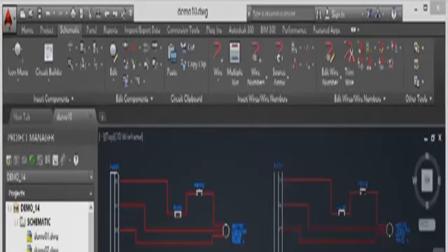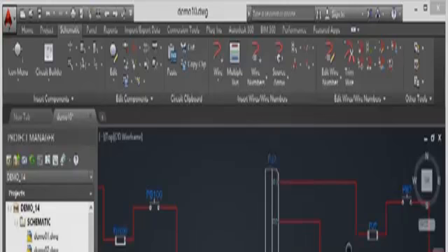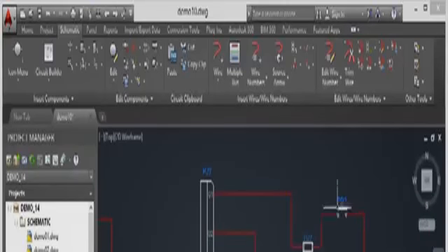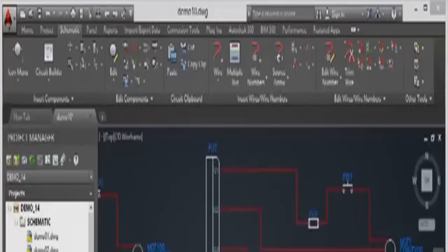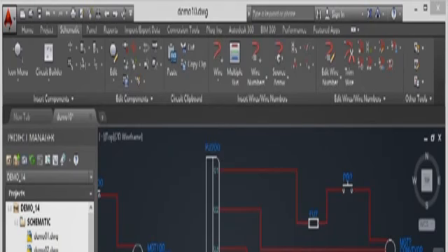Click on OK there. There's my circuit there, an exact replica of the circuit on the left. I just click, and it comes into the drawing, and as you can see, this has now got PJ question mark, FU, fuse question mark, push button question mark, and so on, because it all needs to be tagged. Now what I can do here is I can tag this individually, very, very easy to do. I just select the component, right click, edit component like so, and I can change that there to perhaps PJ200. Click on OK, and that updates. Very, very easy to do.